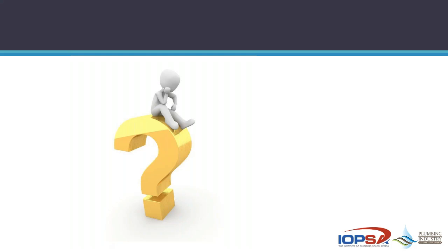And like I said, the standard requires an open vent for each installation. The others you can put two-way vent valves if you want to waste that money. But if a system is properly vented, then the need for that two-way vent valve is almost null and void. Because if you're venting the highest point or all the long branches, there shouldn't be any requirement for anything else. But yes, it's very important because you're not only venting your drain, you're venting the whole sewer system. And I think that's just about it.